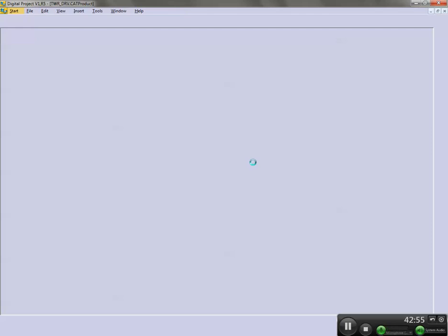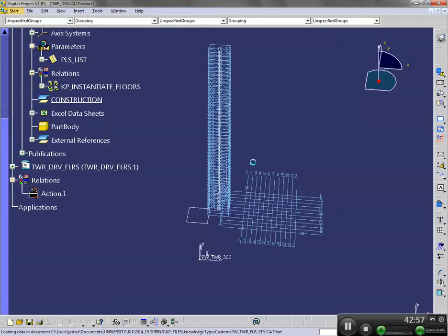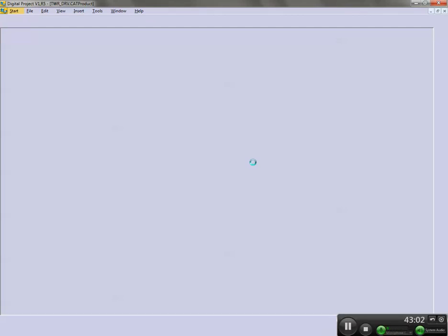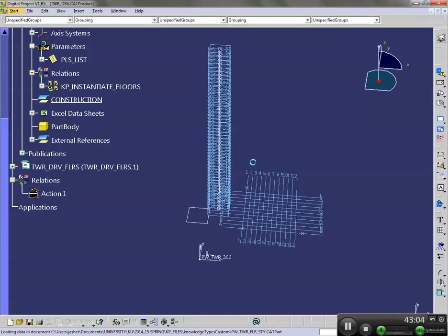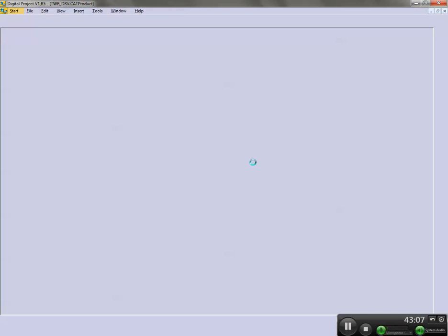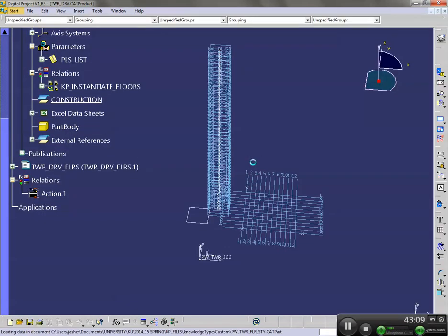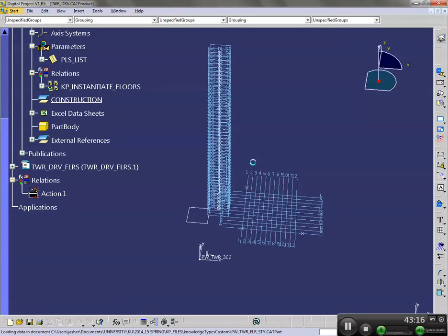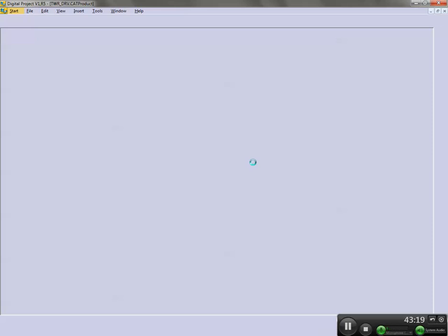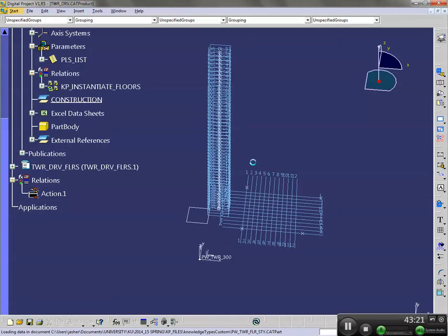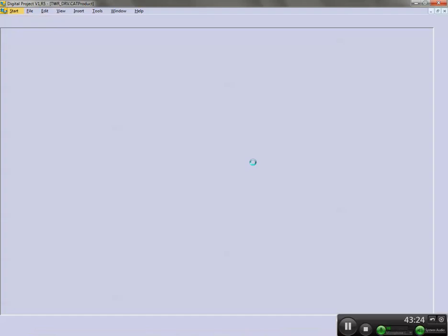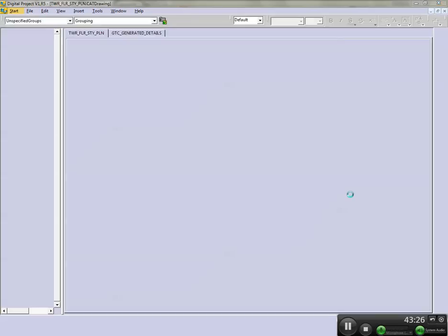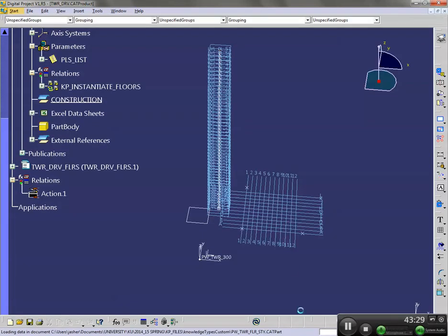If you wanted to add detail after these are instantiated, you'd have to go level by level and add a wall, level by level and add something else. But since this is all contained in a document template where the generation of it is automated, you can go back to the original document template, make your tweaks, add your details, and then regenerate it, using the computer to its fullest, really.